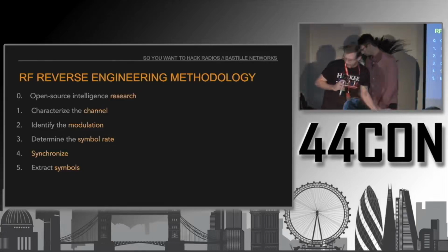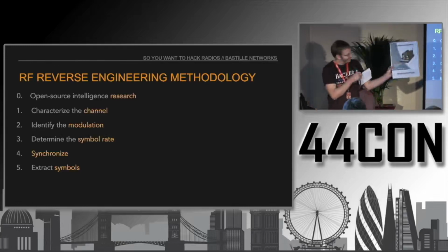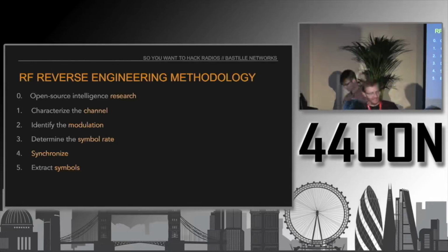Okay, so this device is a Q wireless calling system. Doesn't really have a brand name. Kind of a shitty device we just got on Amazon. Unfortunately, it doesn't have an FCC ID. It's not licensed apparently to operate in the U.S. We do have this user manual here, which tells us the working frequency is 433.92 megahertz. So this gives us some insight about where the device is going to operate on the spectrum. Unfortunately, that's really all the data we have from the manual about how it operates from an RF standpoint.